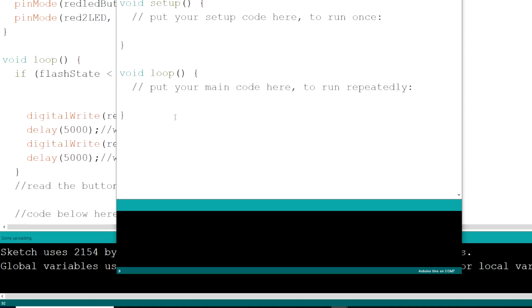Even though our little Arduino is not powerful by computer standards, where a modern computer runs at something like 3,500 megahertz with multiple cores, 16 million times per second is very, very quick. What we're going to look at today is not only how to write our code so that we don't block things, but also some of the very simple things that slow our code down. To start with, we're going to look at what I call the blocked blink example.